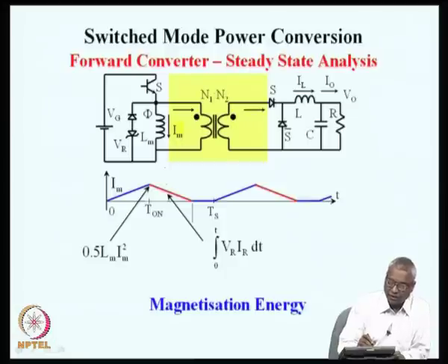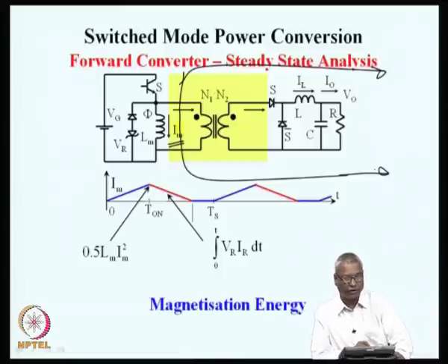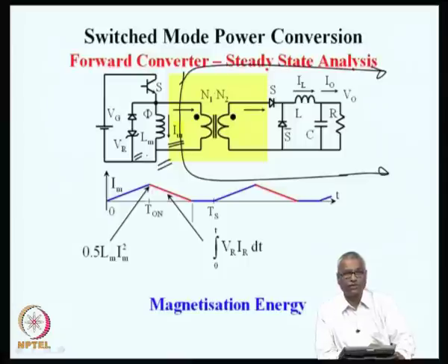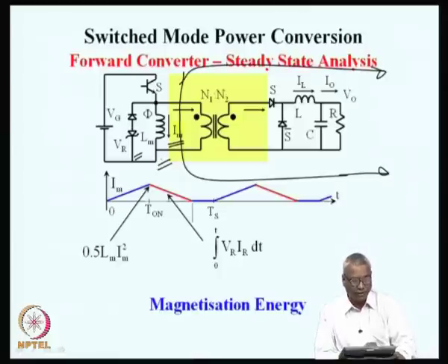We can see that as far as the magnetization current Im is concerned, we have replaced the rest of the circuit as an equivalent ideal circuit on the right hand side of this border, and what we have here is a magnetization inductance and a magnetization voltage, which normally is realized by a Zener voltage and a diode, and this part of the circuit can be separately seen.